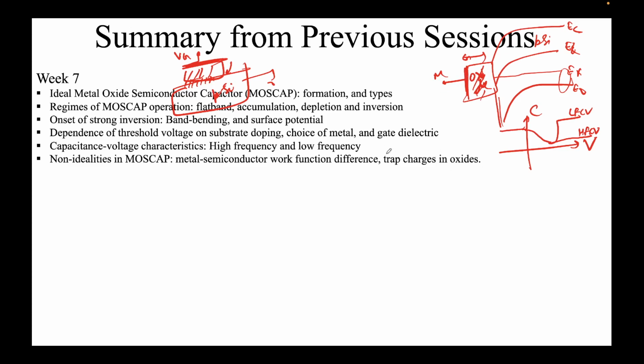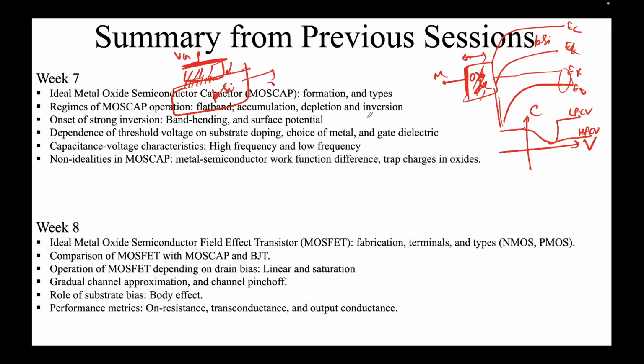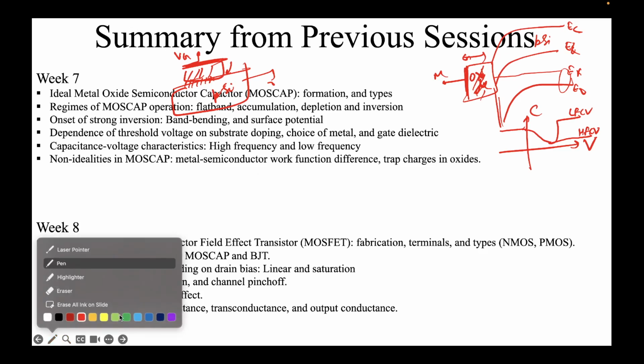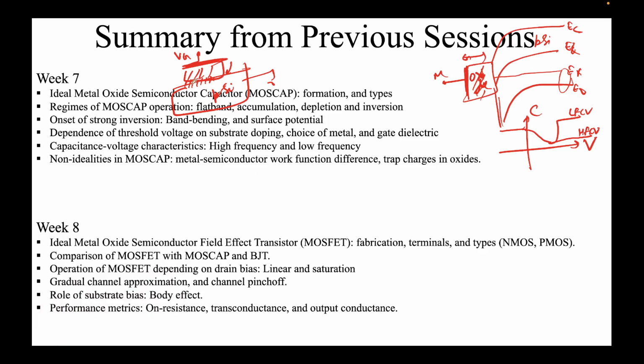Again, these we need to apply some voltage, which we call the flat band voltage, because that's where our analysis started. Then essentially the MOSFET: what you had was this MOS cap, and what you essentially do is add two more terminals. On this side you add the source, and on the other side you add the drain, right? This is the gate terminal, and this is the body or the substrate terminal. For a p-type semiconductor, you make them n++. This n++ is essentially to make the non-rectifying contacts, as I denoted earlier.